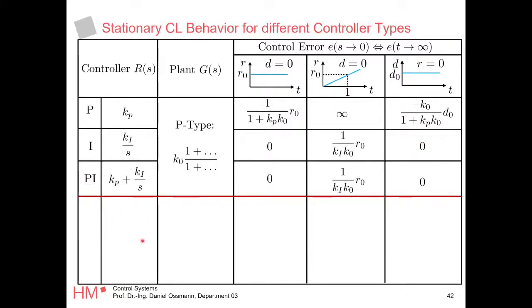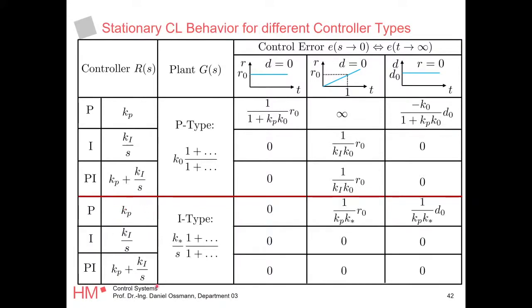In the second part, we're going to talk about integrating systems. The only thing that changes here is that we now have a pure integrator. This part here is still proportional. We are adding a free integrator. So what we figured, whatever controller we are using here, a proportional or integrating, we are ending up with no control error, but be careful, this system is not stable.